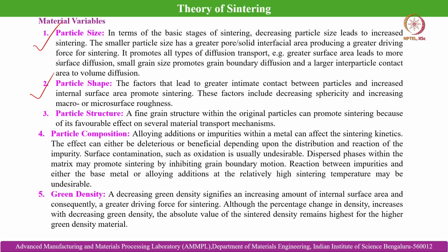So, the factors that lead to greater intimate contact between particles and increased internal surface area promote sintering. These factors include decreasing sphericity and increasing macro or micro surface roughness. So, this is the effect of particle shape.